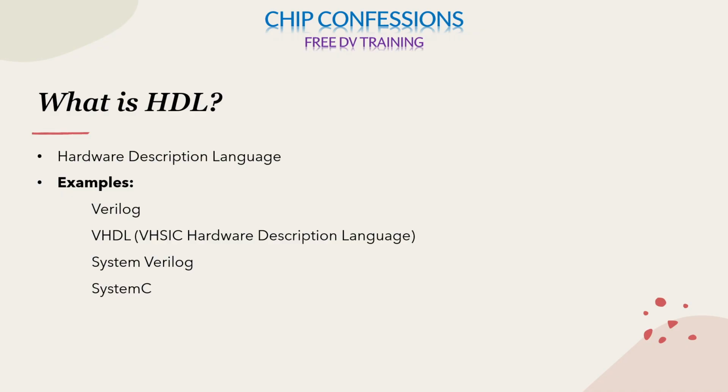But what we can do is high level modeling, like system level designing, with System C. Proper hardware synthesis we can do with Verilog, VHDL or System Verilog, while System C works at a very high level and is not used for synthesis.